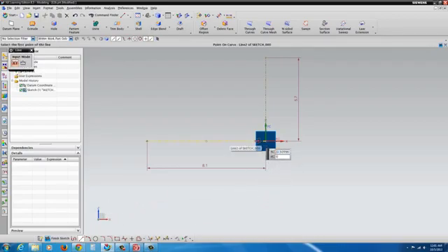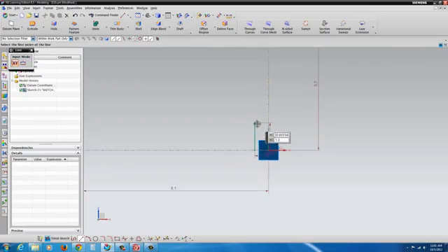Just a little bit off to the left here, I'm going to click and drag up 1 inch, approximately a 1 inch high line. And then off that, click and drag a short little line, about 0.4-ish. And then off of that one, click and drag an angled line, but don't let it contact the center line. Keep it above the center line, just like I have here.